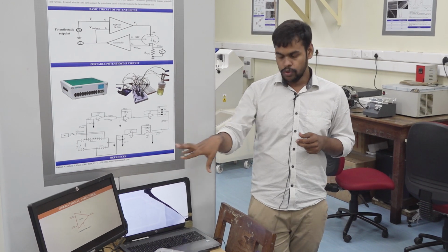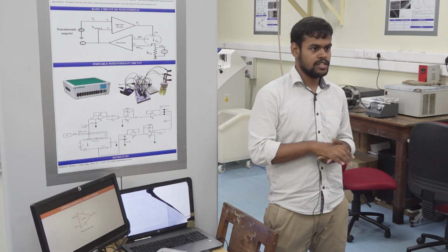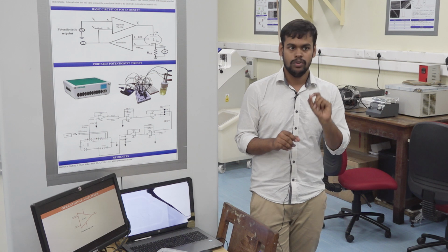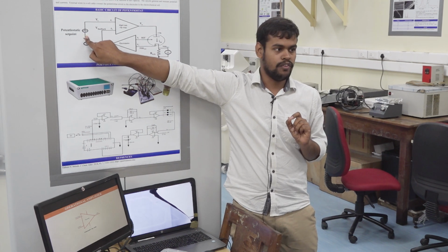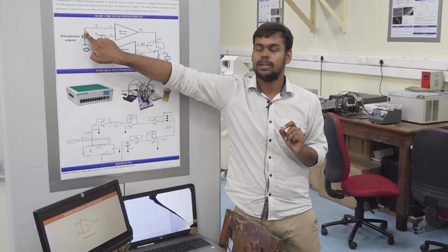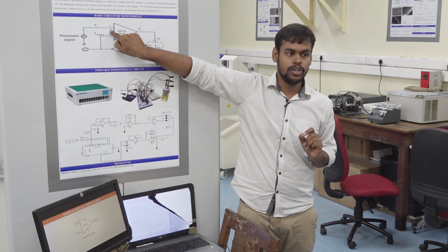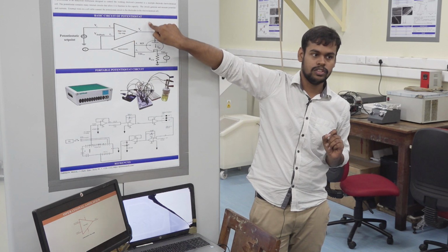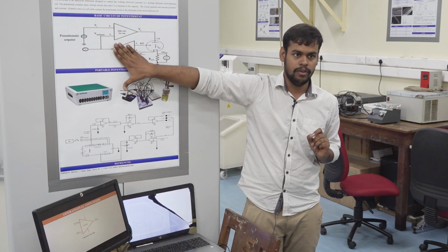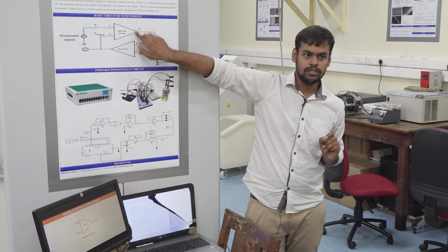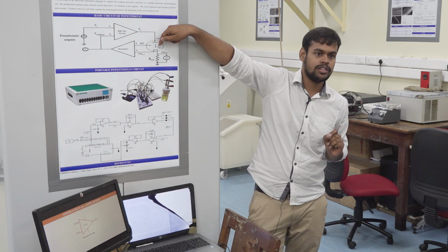Now, you know the op amp, what will happen? When you do a potential scan in the potentiostat from a certain value, from minus 1.5, let's say, to 1, the potentiostat has applied minus 1.5 volt. This minus 1.5 volt, from the potentiostat set point, will go to the non-inverting input. The non-inverting input will apply that to the V0. There will be a certain output from this operational amplifier. This V0 or V out will go to the counter electrode.